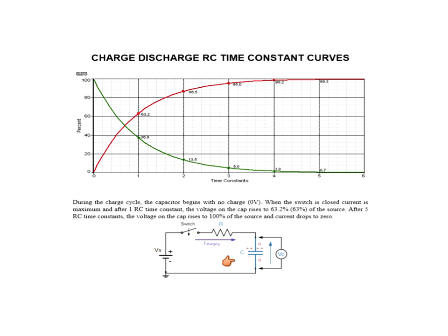We've covered this material in second quarter, charge-discharge RC time constants. During the charge cycle, it takes one time constant, not seconds now, one time constant to charge to 63% of the source. So if this was 100 volts right here, and this capacitor started out at 0 like you see here, when I close the switch, after one time constant, the capacitor would charge to 63%, or 63 volts if this was 100 volts.